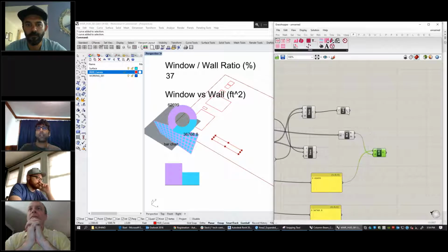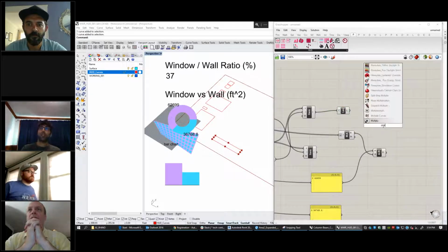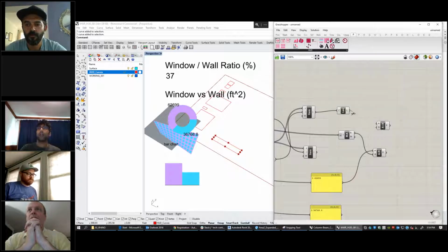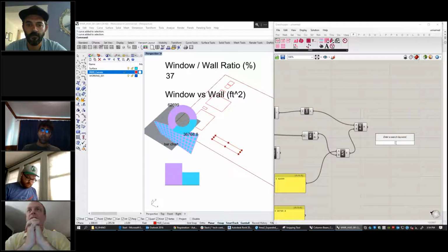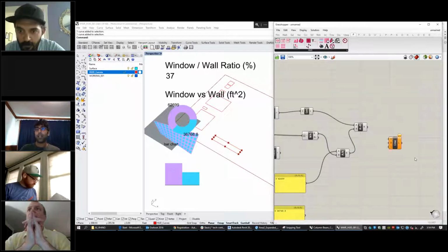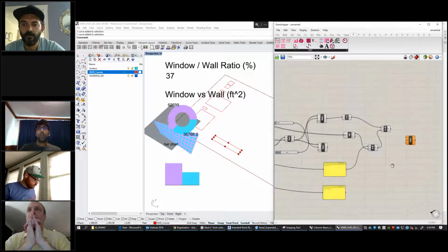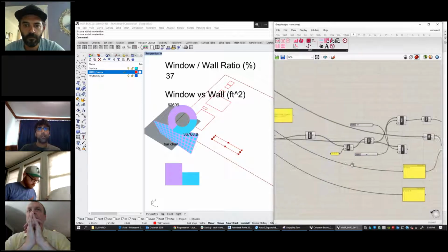It's 0.63, and so the overall length of this rectangle is like 313, right? But I want a rectangle that goes proportionally 0.63 of that. So let's multiply this length by this factor. And then there's this fun little thing called, if you type SDL, it's line SDL. So let's get this little corner piece so we can start from that little corner.